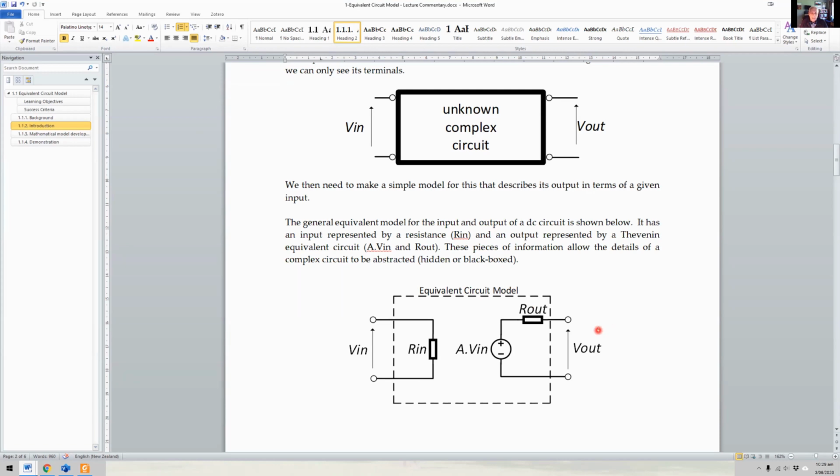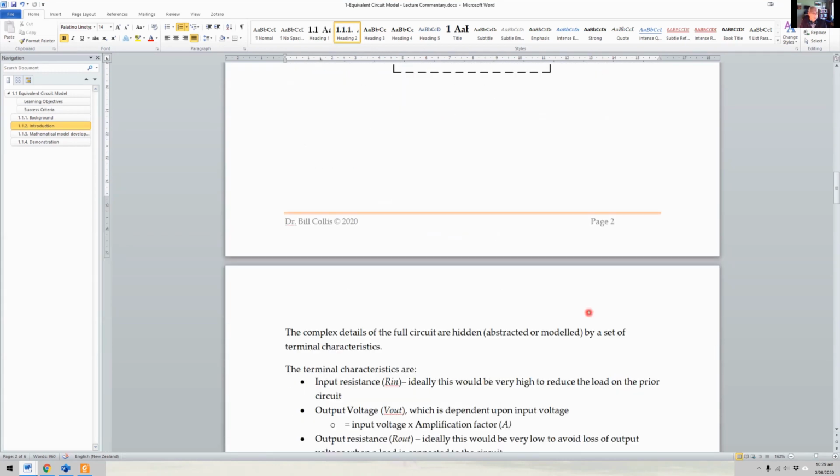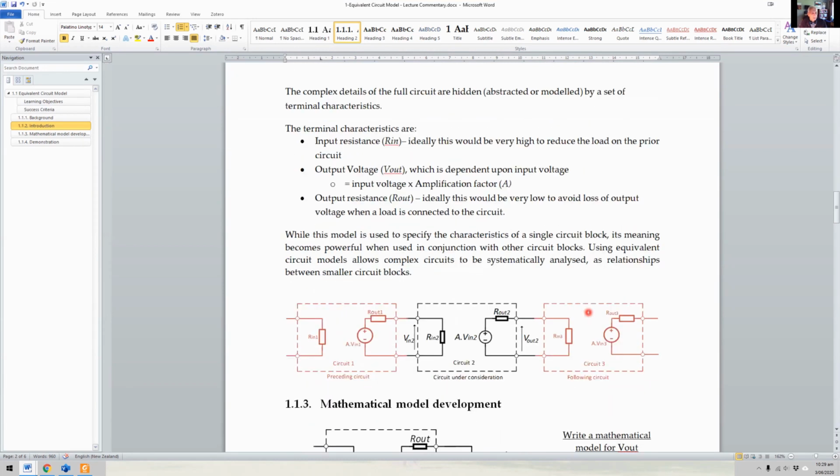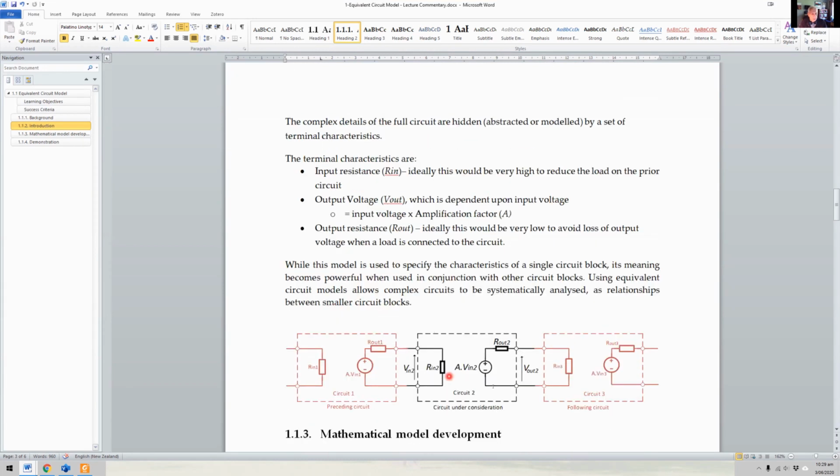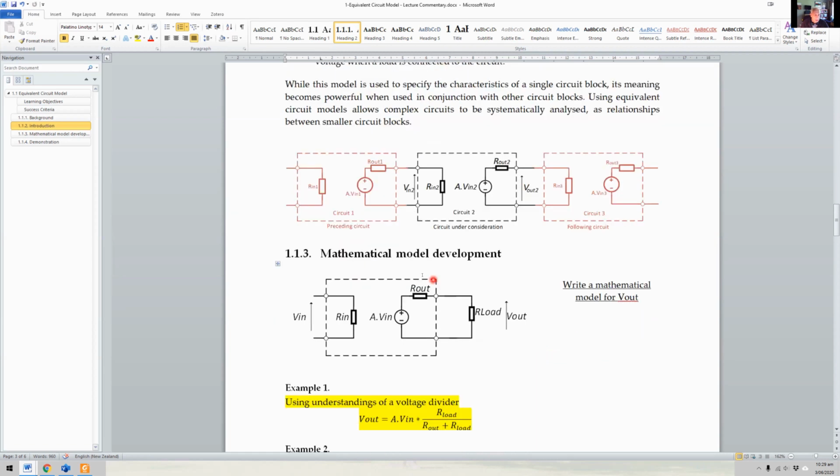And so how do we measure that impact? Well, we know this already, so let's just review that. We've got some circuit which is connected to some other load, and we're going to connect a load to our microcontroller. You can think our load itself can also be replaced by its equivalent resistance. And then we can think, well, hey, this is really simple. This is just a voltage divider. When we look at it, this output voltage is going to be a little bit less than our VCC voltage in our microcontroller, because this has some finite resistance.